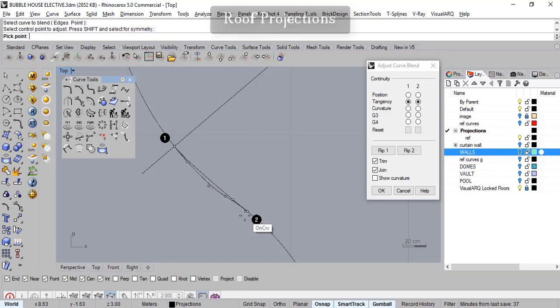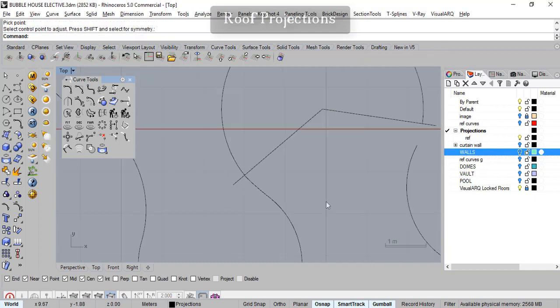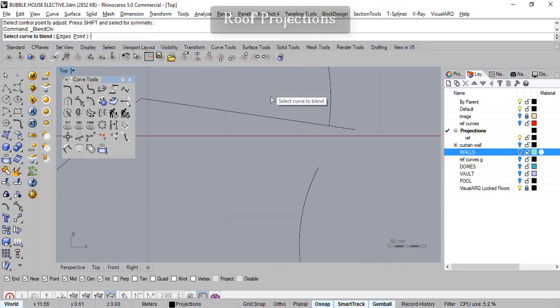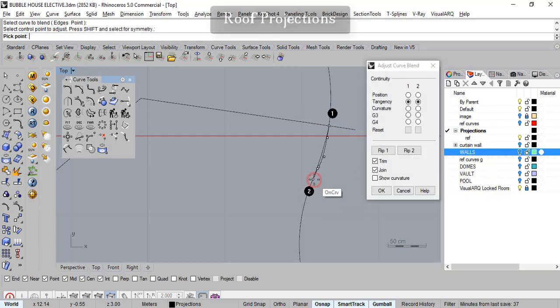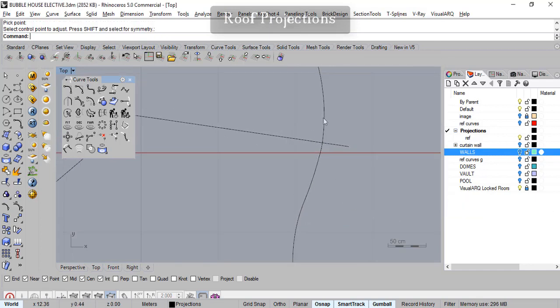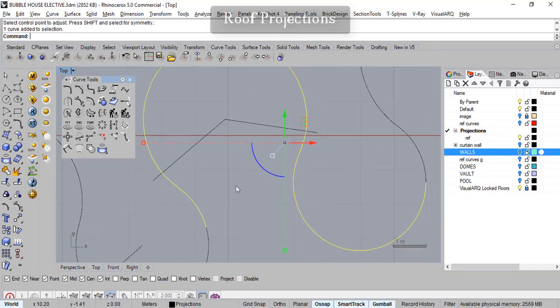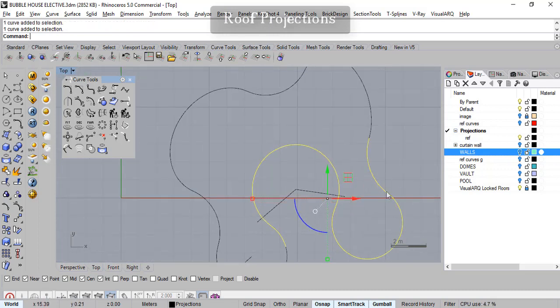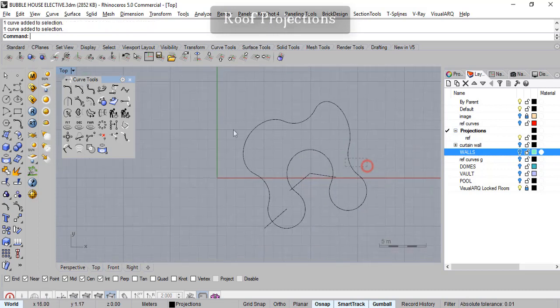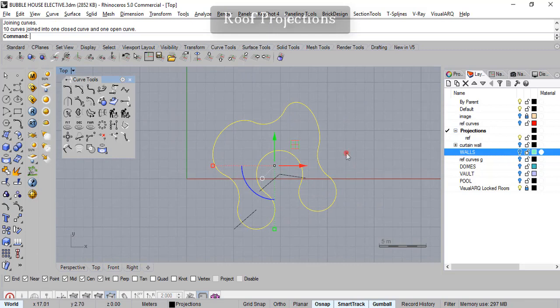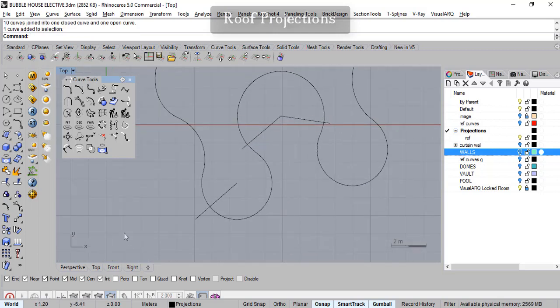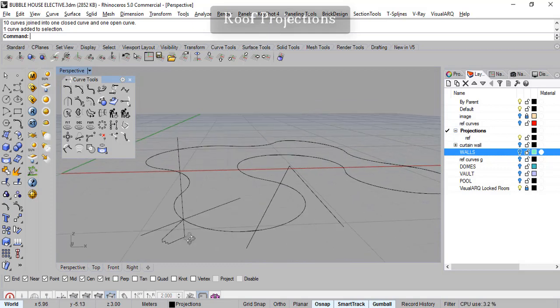You can move this point a little ahead like this. That looks nice. And you can move this slightly ahead. So it nicely trims the extra portion and joins it as well. So we select this, we select the rest of everything. Instead we just select everything in one shot like this. We just join it. The fact that it flashed, it's all joined up now, and we go to the perspective mode. Try doing the sweep now and see the difference.